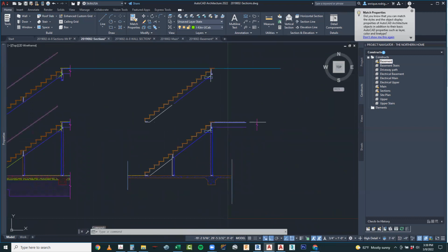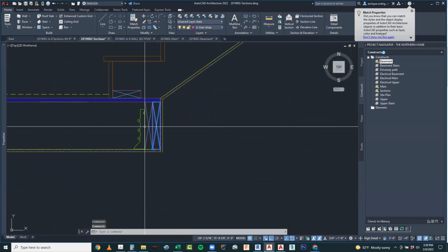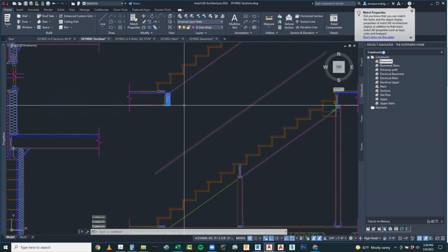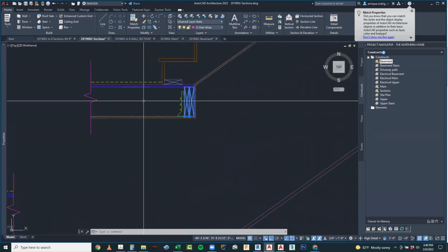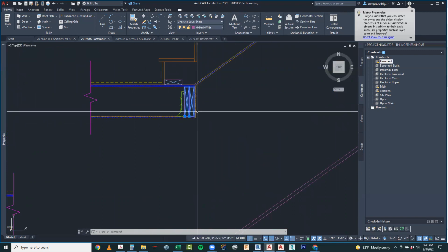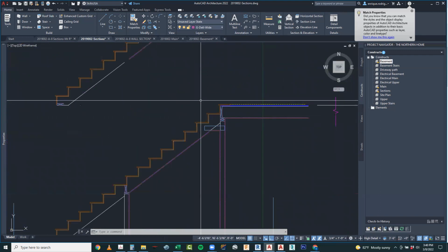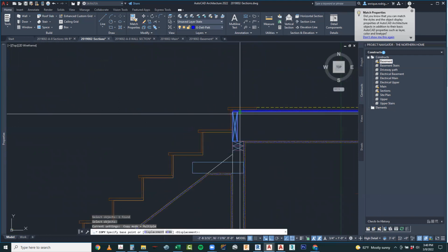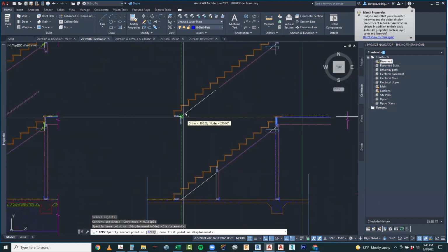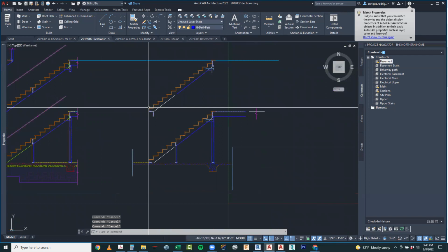You look at your section, you look at his section, he's got what we call 2 2x10, and that's called a girder. It spans between floor joists and actually replaces, these floor joists don't go all the way across, so they hit up against this guy. And they are 2x10s. So let's go ahead and let's copy this guy over. It's a 2x10. I'm going to bring that right to this point. Okay. We're going to copy it again.